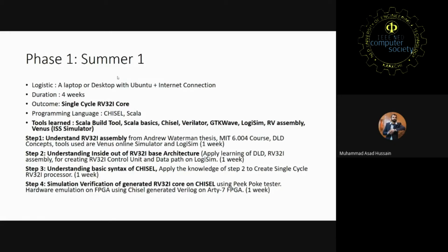The programming languages we are using are Chisel and Scala, and the tools learned in this phase will be the Scala build tool, known as SBT, Scala basics, Chisel, Verilator, an open source tool for simulating the core, GTKWave for viewing the waveforms, and Logisim to design the architecture, the control unit and the data path. Also RISC-V assembly and Venus, the instruction set simulator. So step one is that you need to understand the RV32I assembly.